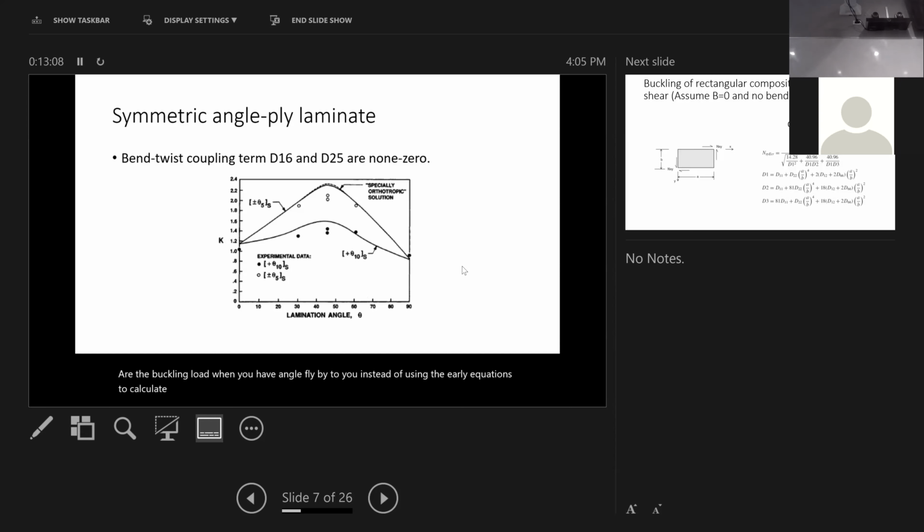It actually gives you, I guess, 50% more than what it really is. The experimental value is the solid circle. So basically, compared to cross ply, your angle ply will have a lower buckling threshold, assuming the material is the same. You just lay up differently, with the same amount and same type of material. So layup has an impact on the buckling threshold.